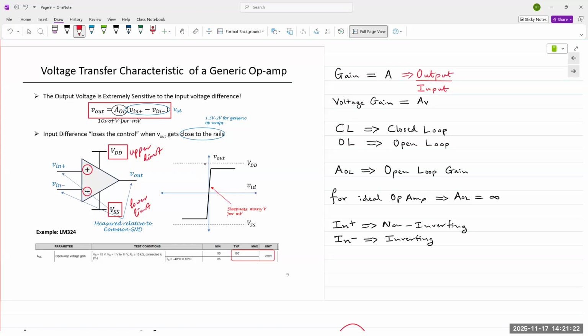So for an op amp, the output voltage is linearly proportional to the input voltage. Vout and Vin have a linear relationship. It's simply multiplied with the gain, AOL. If the gain is 10, every single input value is multiplied by 10. If the gain is 15, 20, 25, 100, whatever the value is, it results in Vout having a linear relationship with Vin. Okay.